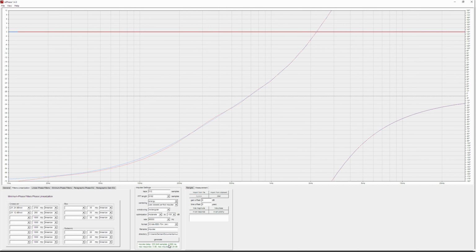Okay, this is, for example, causing a delay of 2.66 milliseconds here. If you are okay with 5 milliseconds of delay, which is inaudible to humans, then generate a delay with 5 milliseconds. As you can see, with even 512 taps, we managed to perfectly replicate this phase correction up to 20 Hertz. There's a little difference here.